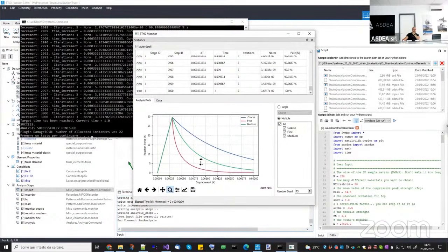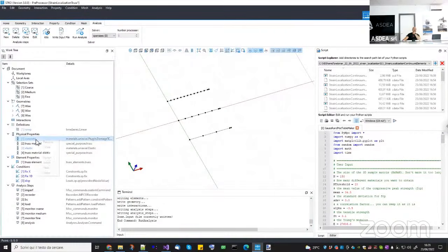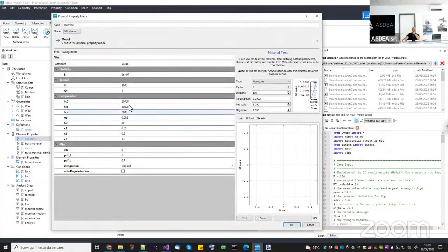Now, in literature, there are many techniques to solve this kind of problem, like non-local models and integral models. They are quite complicated, but the regularization of fracture energy is the easiest one. It can be implemented in any kind of software, and we have it in OpenSees. Now, how do you solve this kind of problem? The concept is that whenever you define a material model that has softening, you should introduce a fracture energy as the area underneath the stress displacement curve, not the stress strain curve.